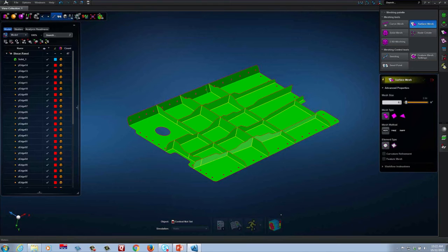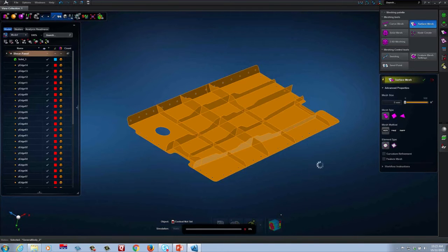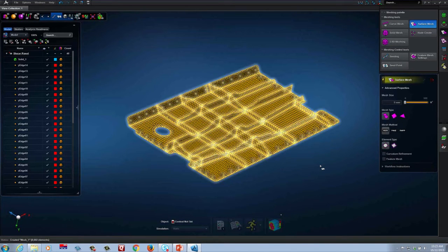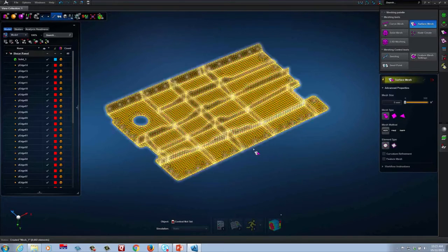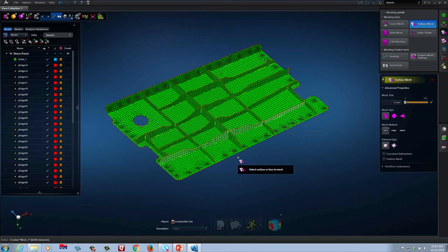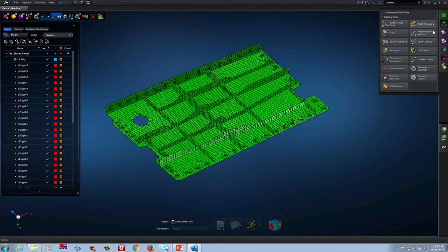I'm using inches today, but I remember a good mesh size in millimeters, so I'll go ahead and enter it in millimeters. And that'll also illustrate the fact that MSC Apex understands units and unit conversions on the fly, which is a very cool feature. So we've actually got a mesh now. You can see we've got some nice washers around the holes, but I really don't want the holes in this case because the fasteners might be represented as a point-to-point type connection using a bushing element, a bar element, such as that. So I'm going to get rid of those holes.